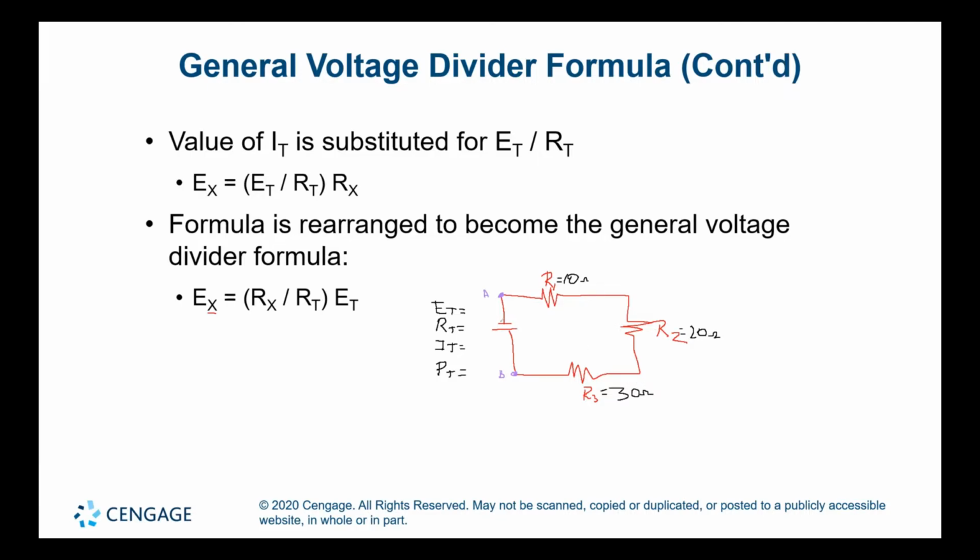So I'm going to say that my power source is equal to 120 volts. That means that when I use Ohm's law, we can do this 2 different ways. Off the top of my mind, I would be able to say, well, 120 divided by 60 is going to be 2 amps. Okay, but what I want to do here is just to show you how to get this voltage here, which is E1, without having to do any other calculations.